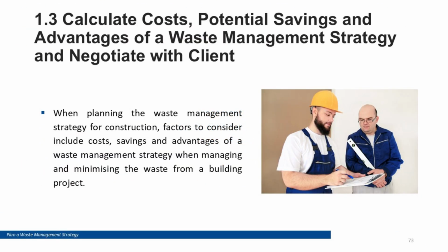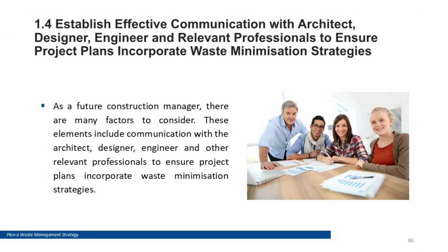Waste minimisation is also a cost decision. Disposal fees, transport and handling time can be significant, especially when waste is mixed and cannot be recycled. A basic cost comparison helps justify the strategy. What landfill would cost versus what can be saved by better ordering, reuse, recycling and supplier take-back. When discussing the strategy with a client, focus on clear benefits: reduced cost, improved safety, stronger compliance, and better environmental outcomes.